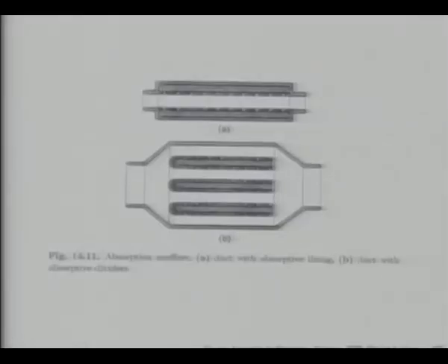Now this is the picture of two types of mufflers where the reliance is not that much on expansion or reactive mufflers, but these are dissipative ones. So you have lining inside the tube which absorbs sound, and in the second one what you have is corrugated, so the absorption area in the expansion chamber gets enlarged, and that enlarged area surface is coated with absorptive material, so that absorbs sound. So your B is like a hybrid. You have an expansion chamber and also absorptive dividers are there.